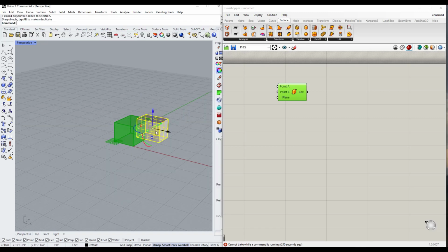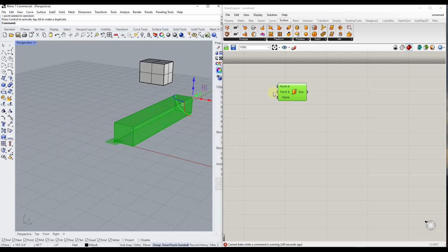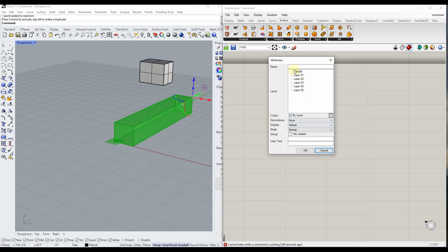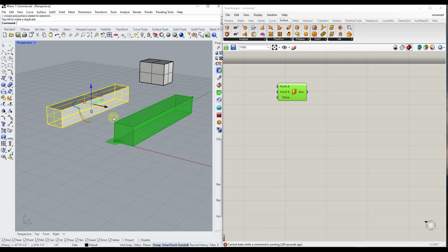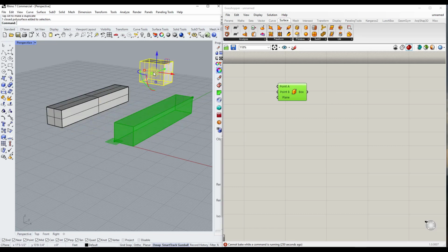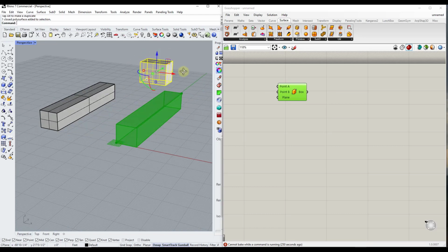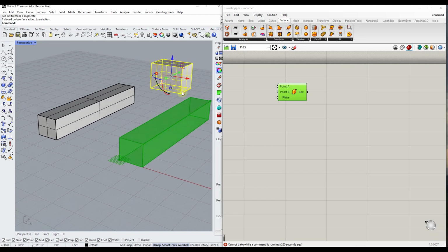Let's say I was to make an adjustment here and make this really wide, and then we right click and bake it. Again, we call this box 2 and hit OK. That's generated another box over here, but notice how that didn't have anything to do with the box that we created over here. This box is created, it's done, it's baked, it's complete.